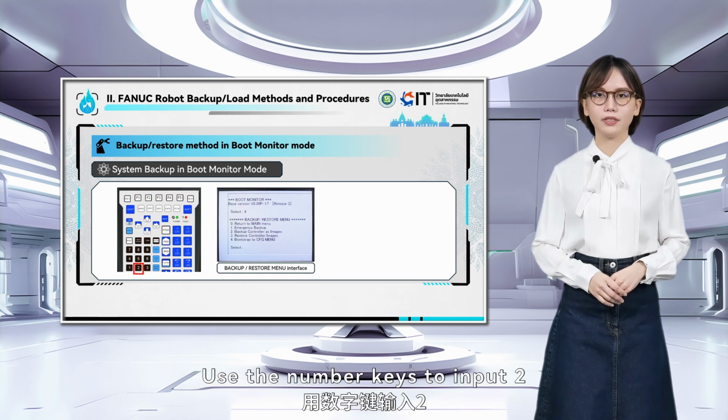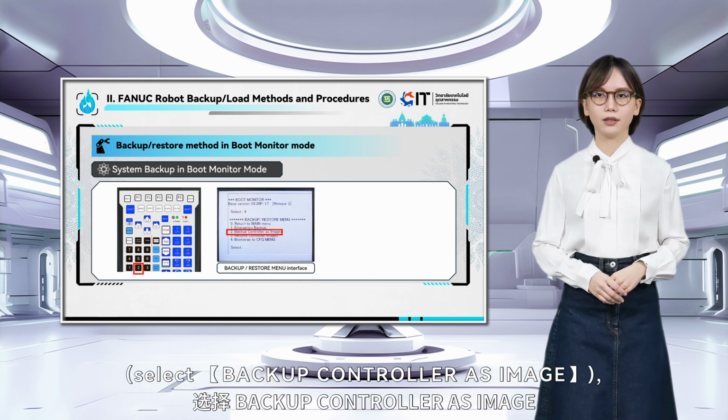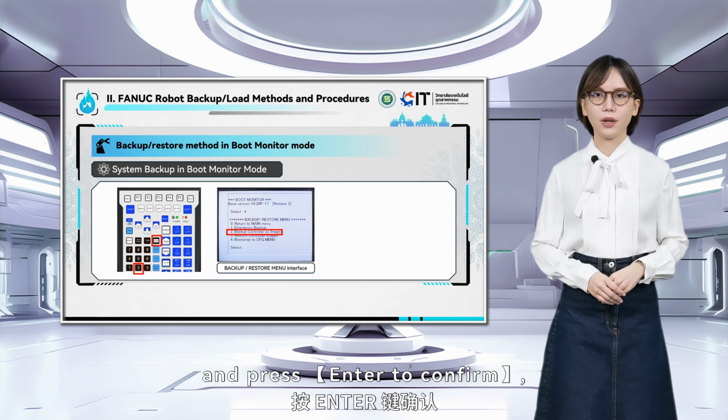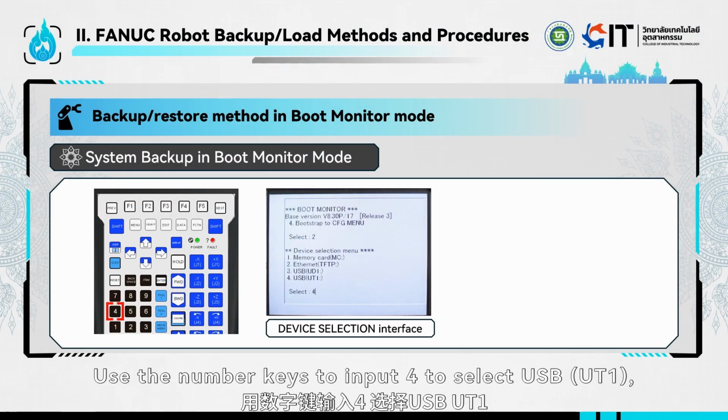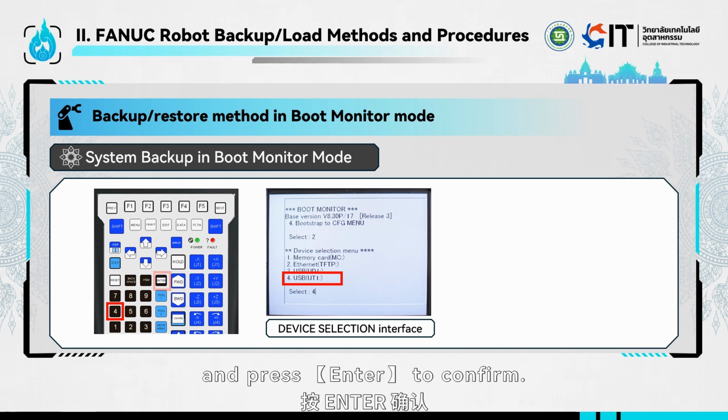Use the number keys to input 2. Select backup controller AS image and press enter to confirm, entering the device selection screen. Use the number keys to input 4 to select USB UT1 and press enter to confirm.